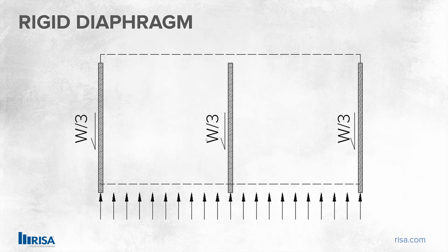Also, the diaphragm, you can see, is going to move together, right? Because of this rigid connection, we're going to have this deflection and this lateral movement that is the same everywhere. So in our model, we're calling our composite floors on the lower levels rigid.